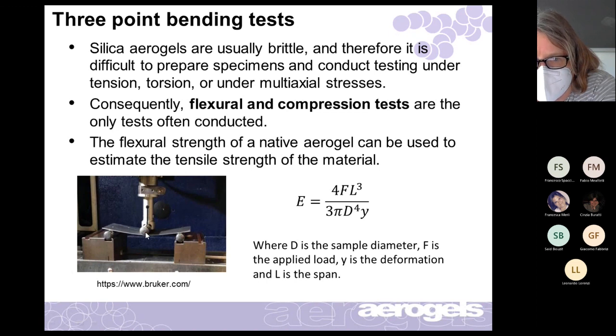1, 2, 3. So you can relate the information you get, which is basically the deflection of the material as a function of the applied force, to that modulus, right? So F is the force that you apply here. L is this distance across your sample.